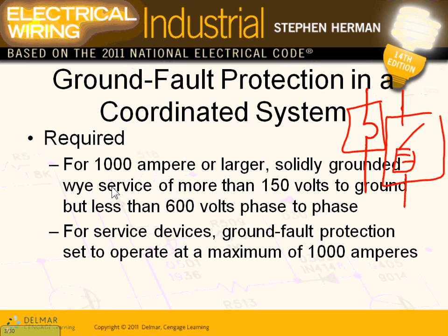There's another device they also use, called ground fault protection. Ground fault protection is required. Let me tell you where the code is, because I know you all care about the code, right? Yes. So the overcurrent protection device on the service, 230.90, will get you to 230.95. If you go to 230.95, this article talks about the service.